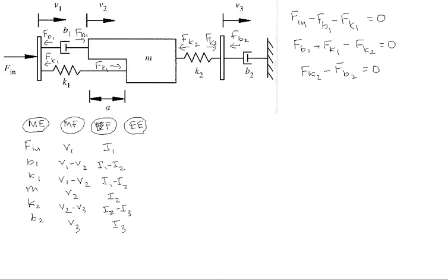The next step of incorporating the electrical flow is very straightforward, and completing the table with the electrical elements associates the voltage source to force, resistor to damper, capacitor to spring, inductor to mass. Let us next try to construct an electrical sketch.